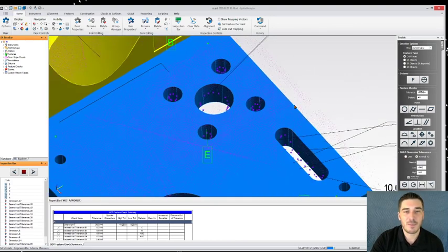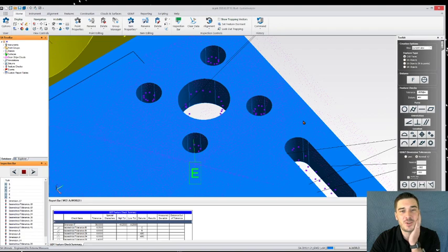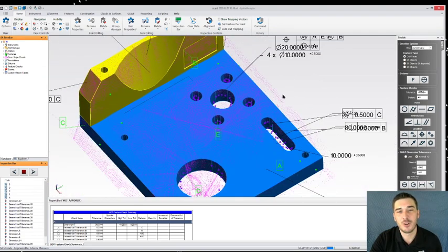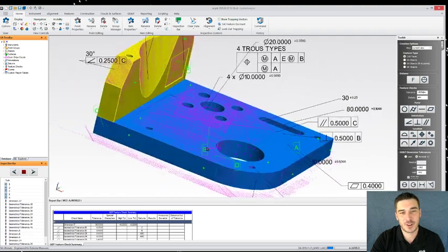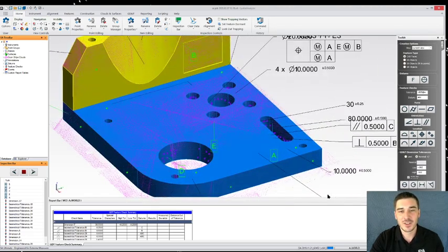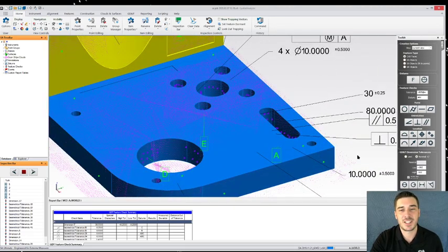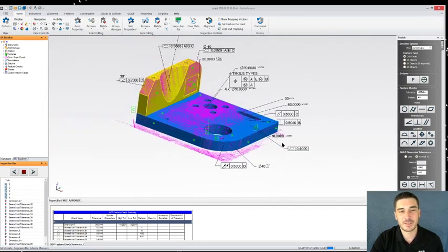So if you're a metrologist, you might be used to using a probe to be able to capture really good resolution data inside of a hole. And then you can use the scan to capture the surface data of your part as well. So this is a common way that GD&T is evaluated, using both probed points and cloud points.